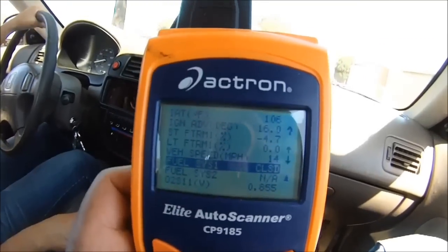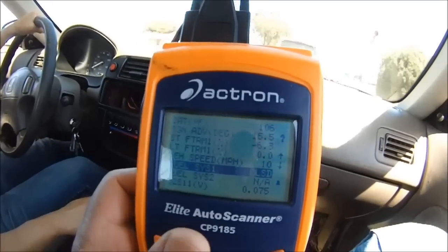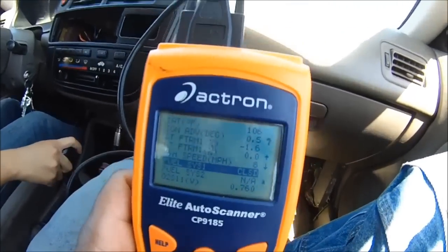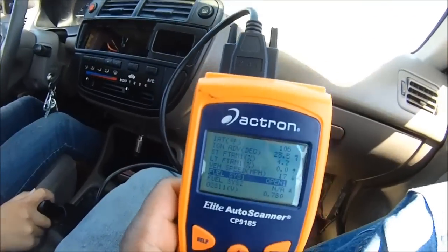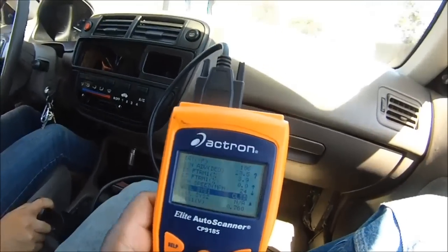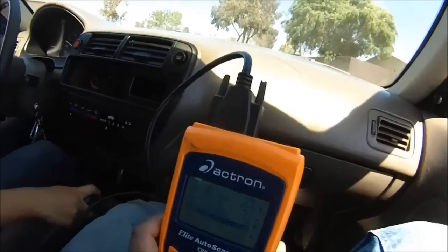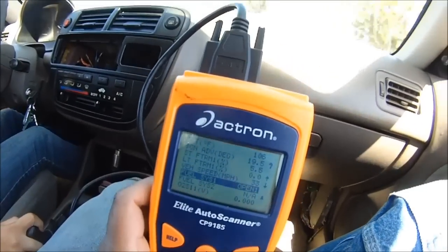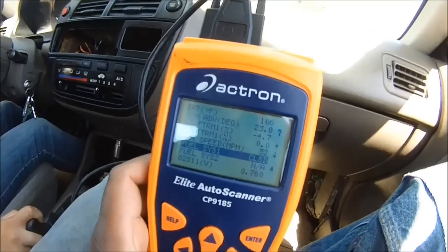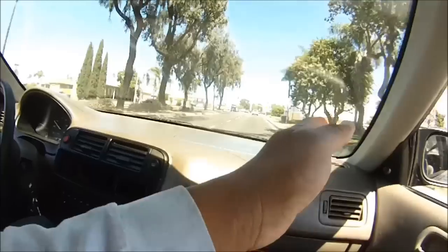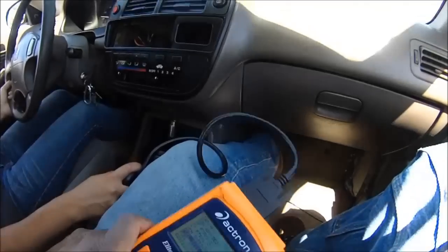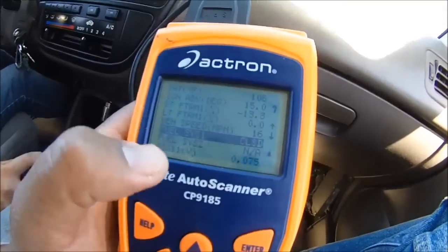So there's already a preset programmed learning block inside the computer system here. This is our computer, the PCM. There's already a program set in the learn block area that tells the computer that when you accelerate to a certain speed at a certain engine load, remember, some sensors are still working though, it will automatically enrich the system so you'll have enough fuel to pass the person. That way you don't bog out waiting for the sensors to do it. That's just another reason why it went into open loop real quick.